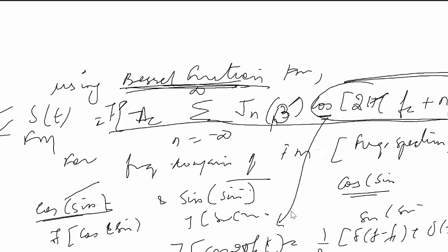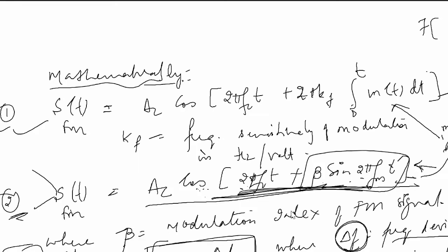And in the experiment, you have to calculate the modulation index. The formula for calculating the modulation index is del f by fm. That is the normal equation in the derivation: modulation index beta can be found by taking the ratio of the frequency deviation to message frequency. So in the lab, when we are finding out the modulation index on the trainer kit, obviously we are not using the second formula.